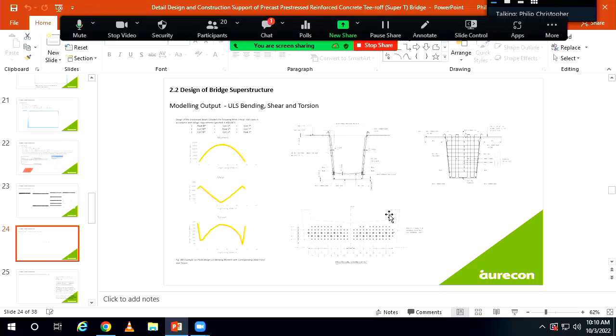So we try to utilize it as much as we can for a big tender design when you're trying to provide a cost-effective method. Whereas a cable stayed bridge is more glorious, beautiful, famous, but it has to come from the client side. This is another layer of contracting and tendering: when the client wants something that adds more intrinsic value to the community, they take the initiative, engage with the architects at an earlier stage of the design, and then tender that out and tell us this is the bridge type they want. Then we will be able to size it accordingly.